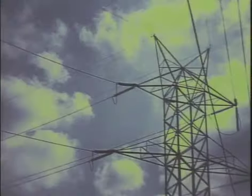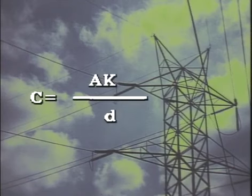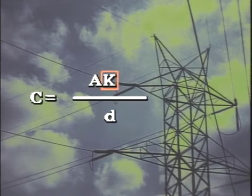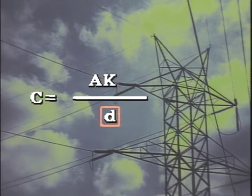There's an equation that's commonly used to find the capacitance of a capacitor, or in this case, a transmission line. Again, like inductance, the equation expresses capacitance in terms of the physical properties of the conductors. The equation is C equals A times K divided by a lowercase d. C represents capacitance in farads. A is the area of the plates. K is a constant determined by the dielectric material. And d is the distance between the plates, or the thickness of the dielectric.